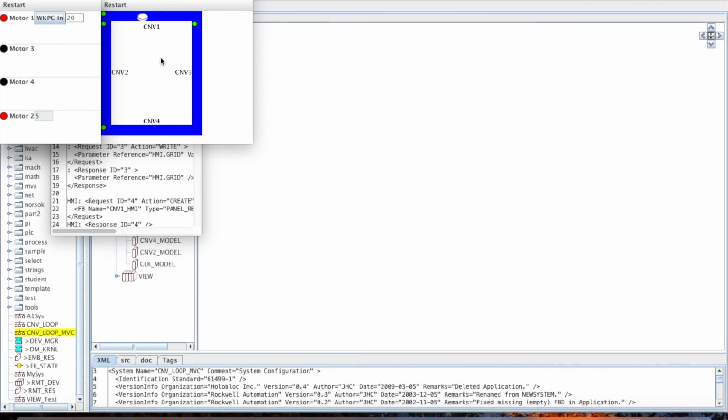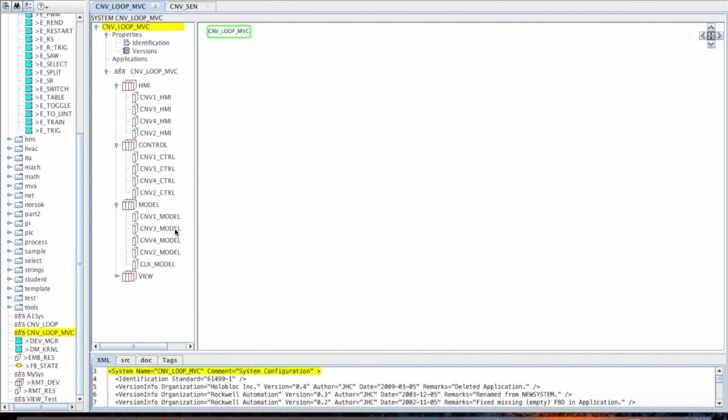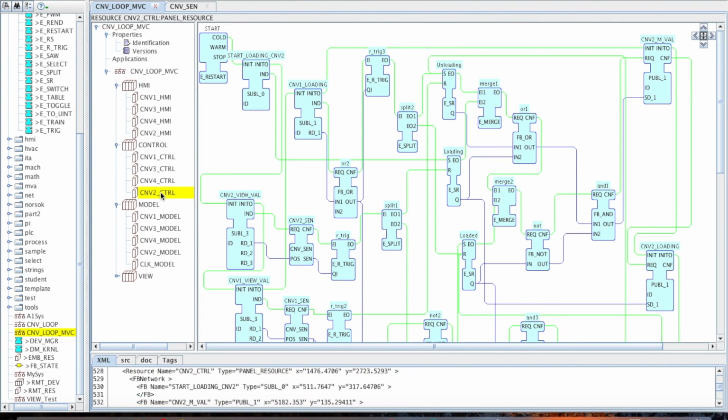Now, as we have a control implemented, we can also see, as with the stuck problem when I ran it previous time, that the controller knows that it won't be pushing the workpiece to the next conveyor when it's occupied. So all of these conditions have been taken into account and implemented in the system. The next step could be removal of the model and connecting it to the actual physical interface.